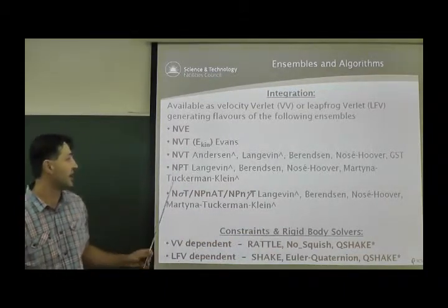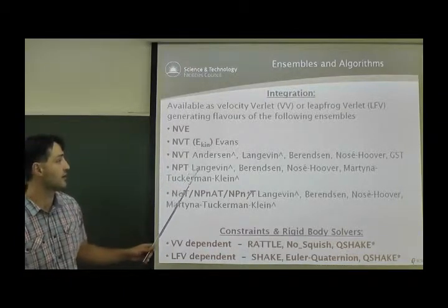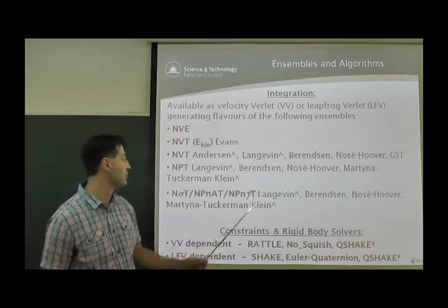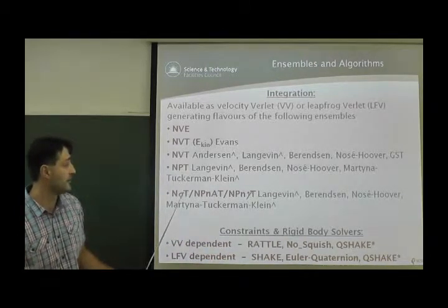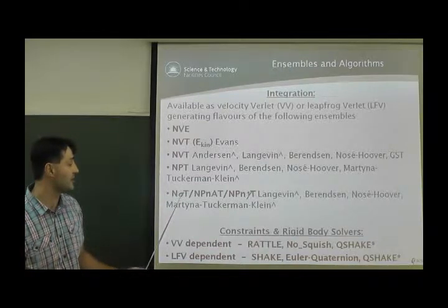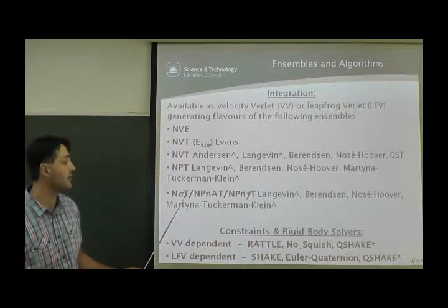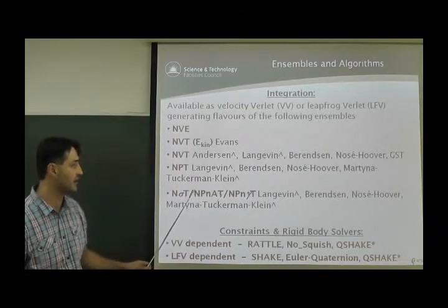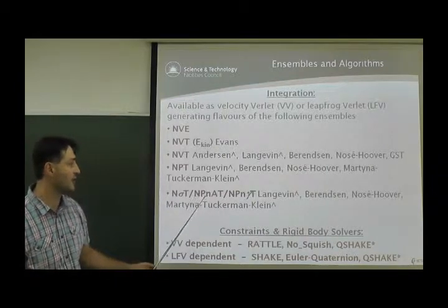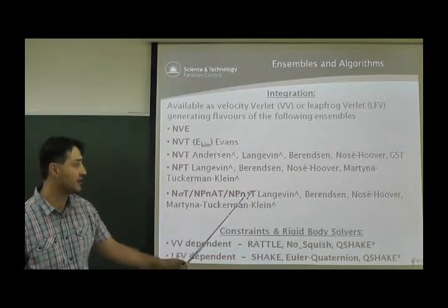We have the isobaric and isothermal ensemble, again various interpretations: Langevin, Berendsen, Nosé-Hoover, Martyna-Tuckerman-Klein. Here we have the anisotropic pressure and constant temperature ensemble, which can be extended to those fancy ones for interfaces and slabs, which preserve normal pressure and surface area, or preserve normal pressure and surface tension.